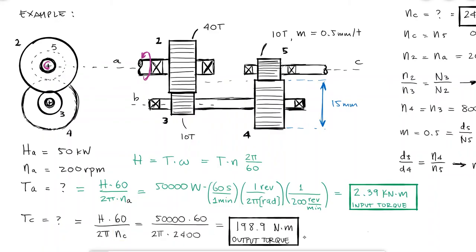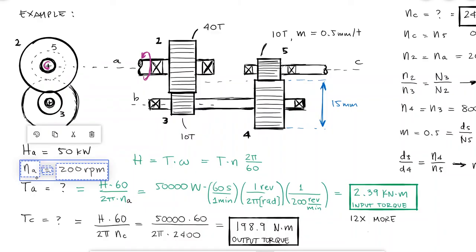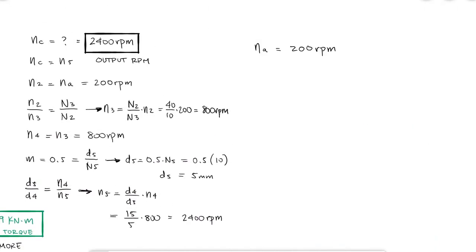As you can see from this gear system, the torque coming in is 12 times the torque coming out, but the output speed is also 12 times higher than the speed I'm giving the system. There are many reasons where you would want to gain velocity even though you lose torque, like for example the higher gears in the transmission of your car, but also you can lose some speed to gain torque, like for example the power screws we studied before.